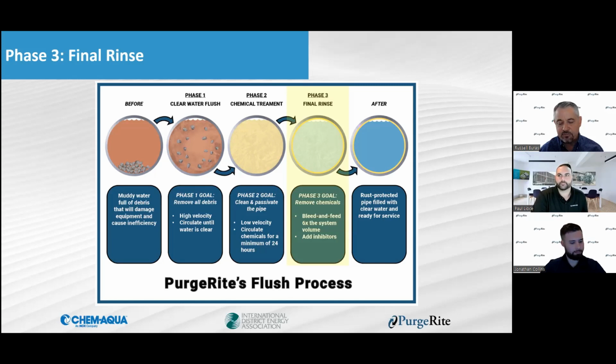A lot of times, the faster you can do those things, the better. You're trying to maintain a lot of different things that are going on in the system, and the longer you go, it's just like you said with oxygen and mild steel, iron content. You're trying to get below typically 1 part per million, probably less than that in some cases, and that's just a typical goal.